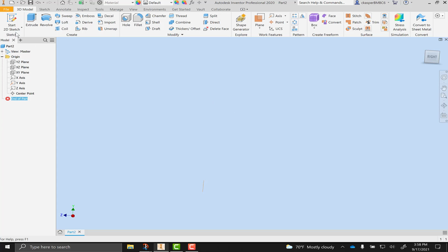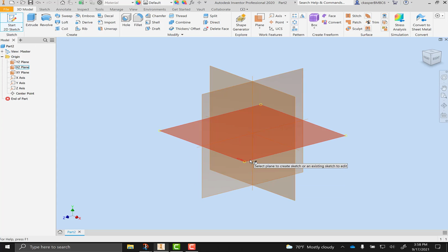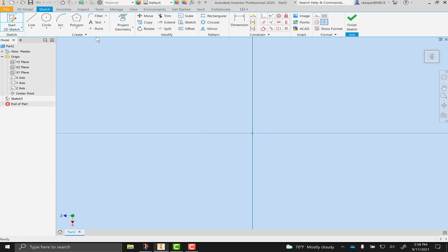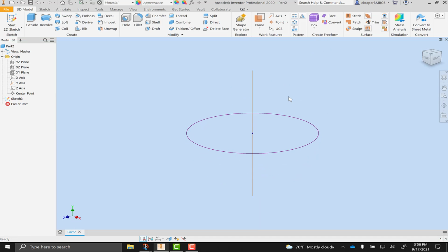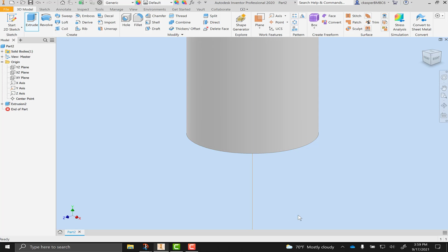So if you were to kind of start over and you were to draw a circle this time, I'm not going to worry about the top thing because it's all round, and we'll make the circle 20 millimeters. How about that? 20 millimeters in diameter. We'll make it 200 tall. Good. And the y-axis is exposed so we can see it. Very good. Okay, let's pick a plane. That one. And let's sketch on it.